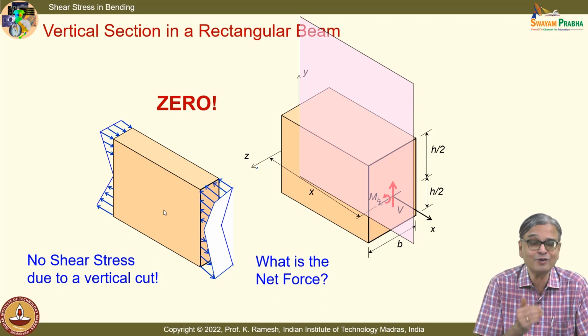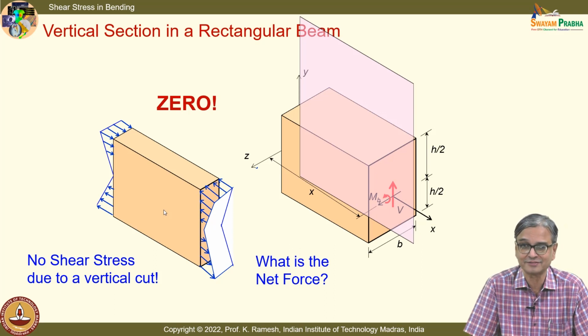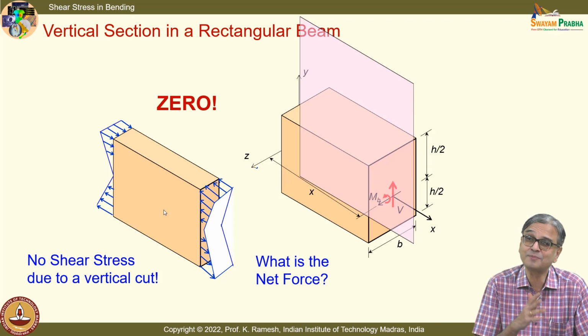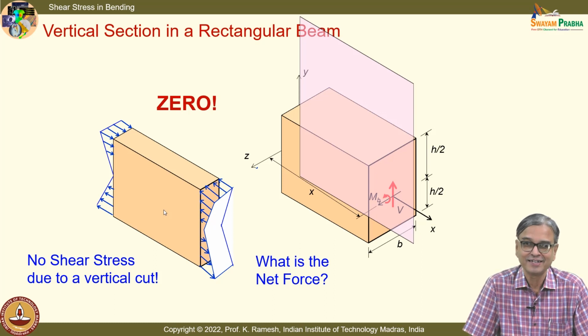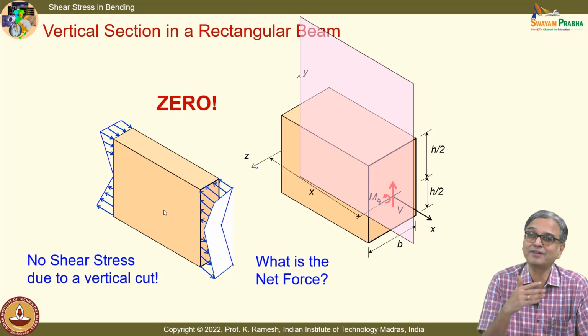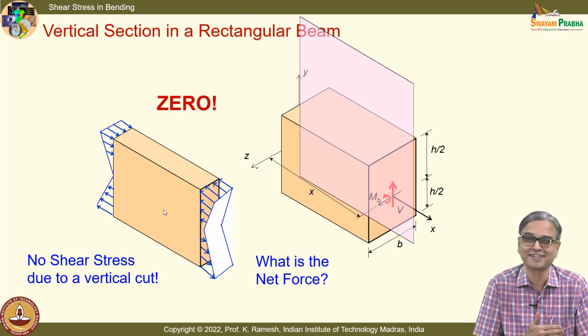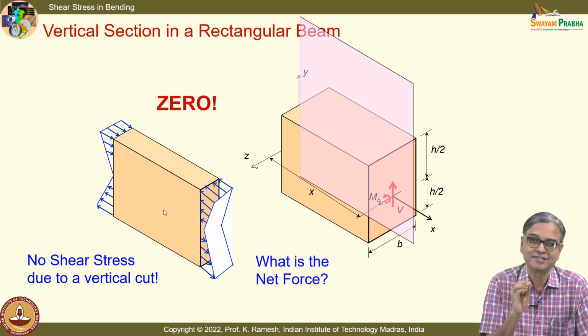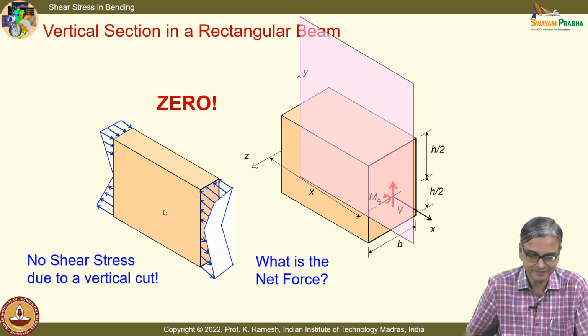Because I am going to take a counter example. I have always been saying shear stress has been parabolic in nature. I am going to show something different. Fine. And I am going to show that when I make a vertical cut, I am going to have something interesting. So, it is problem dependent. You will have to understand how the unbalanced force comes into play. Okay.